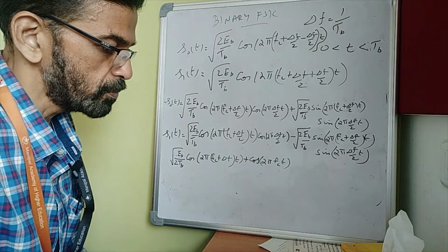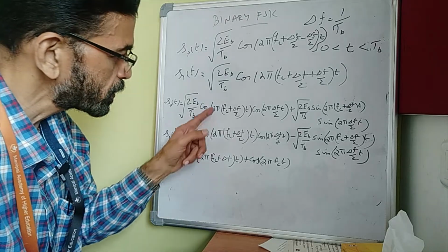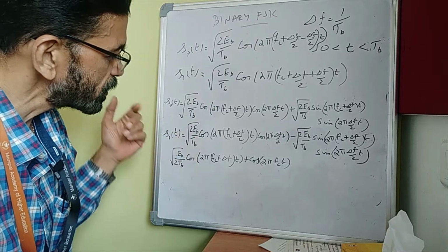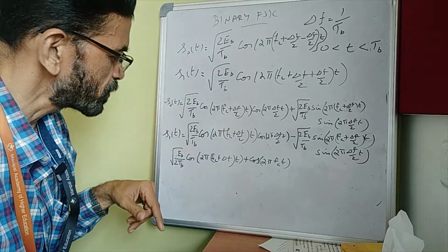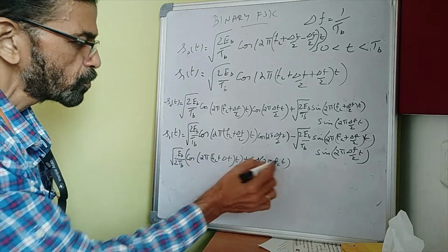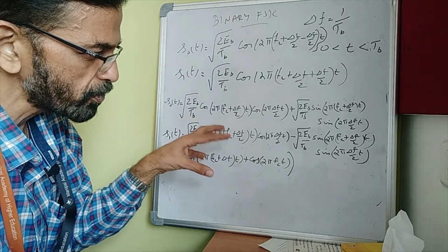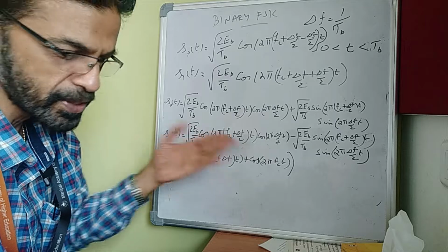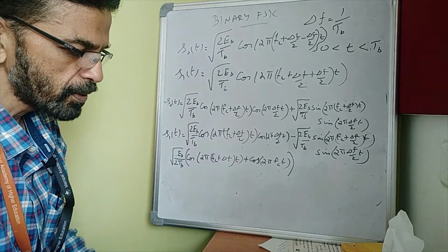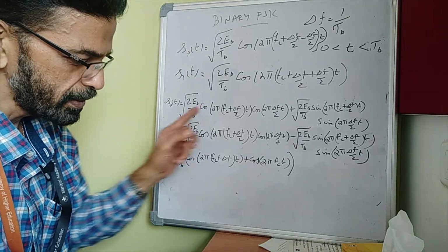So that's what happens to the part that is not changing with the bits. Now we can say that irrespective of whether S0(t) or S1(t) is transmitted, and one of these two is transmitted, the sum of these two sine waves will always be there on the line. So one part of the power spectral density is composed of this, and it is nothing but the sum of two continuous sine waves. So the power spectral density contribution from this can be easily identified.